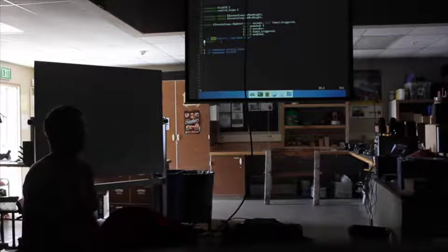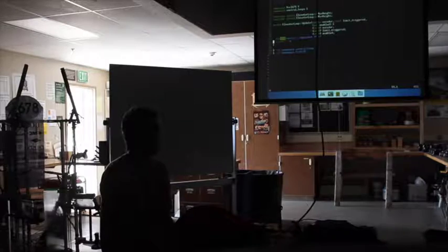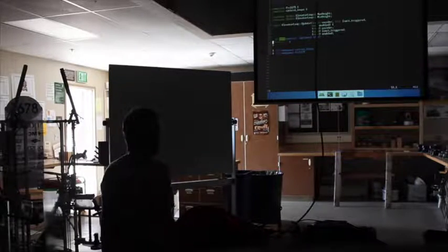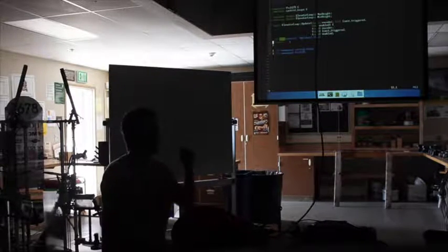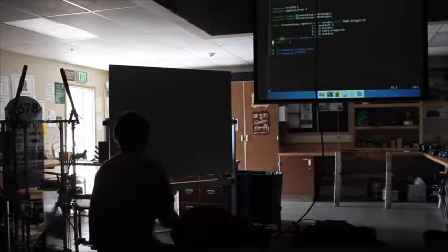Question, when you say zeroing, you mean the zeroing box is going to bring the elevator down to the base? To that position? Yep. This is how all 971 robots work. Oh, okay. You just don't see this part because we move it around. You'll see me wave all the robot pieces around before the match, or one of our drivers. That's me zeroing it. So every time you move into a position, you go down and then back up? No, this is a good question. This is the crux of the problem. So what we do is we only need to do this once, once per startup. So when you turn the robot on, right?